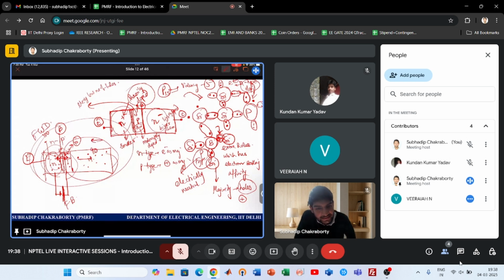Current is flowing in the other direction. Electrons are flowing N to P to N, like this. But actually 10 is not lost, say 5 is lost. Very little, because as you correctly told, the base is very lightly doped and this is a thin region. So how many will combine? Maybe 5, 6, like that, for example. So the remaining 95 goes to the N.